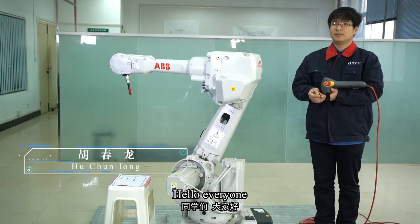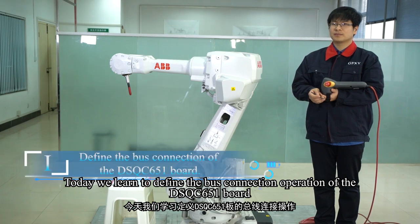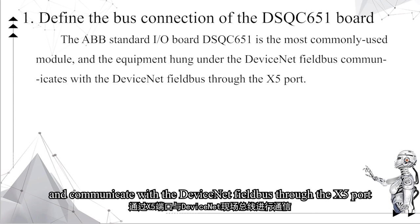Hello everyone. Today we are going to learn how to define the bus connection operation of the DSQC651 board. All the ABB standard I/O boards are devices hung under the DeviceNet field bus and communicate with the DeviceNet field bus through the X5 port.